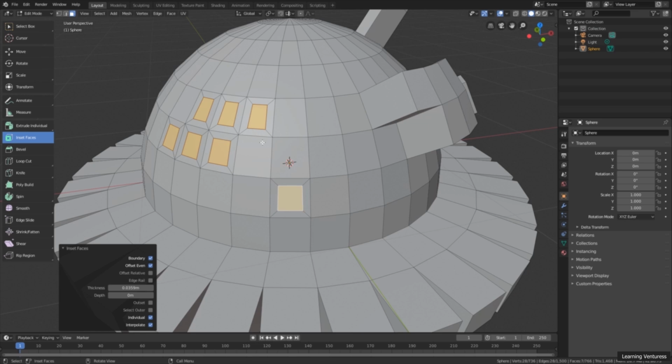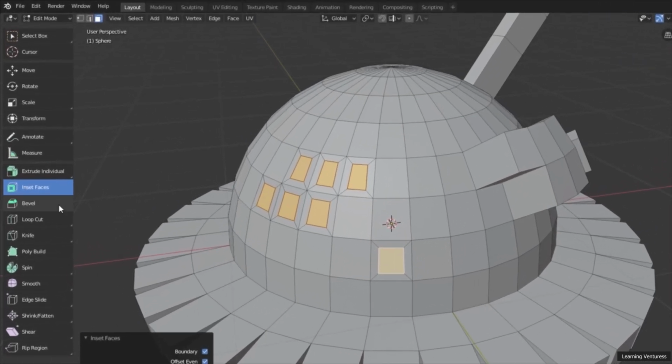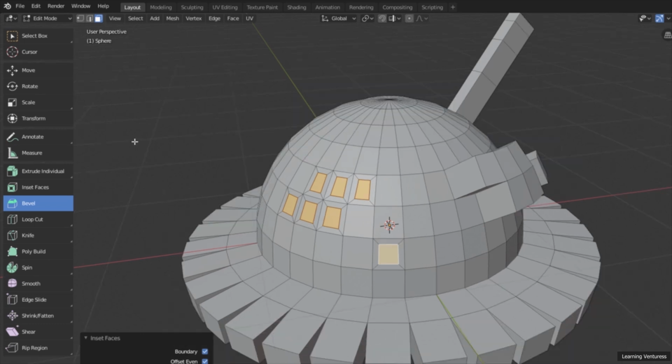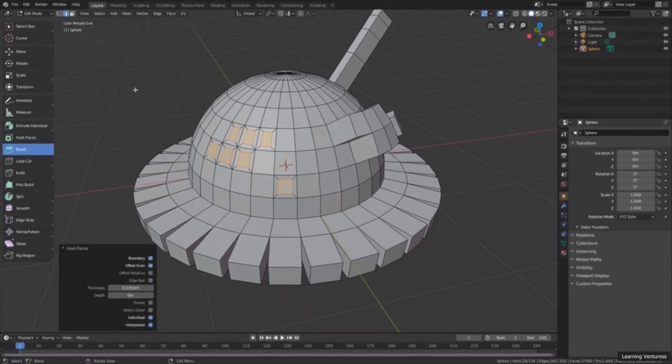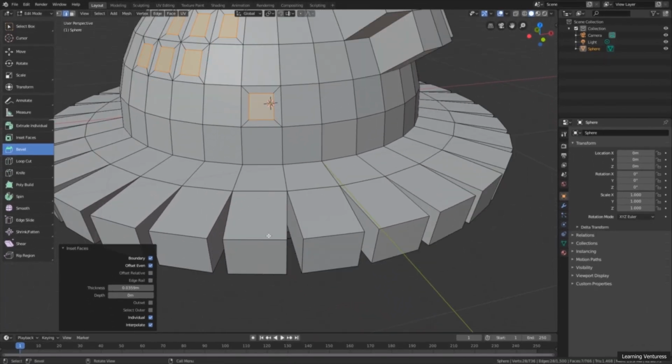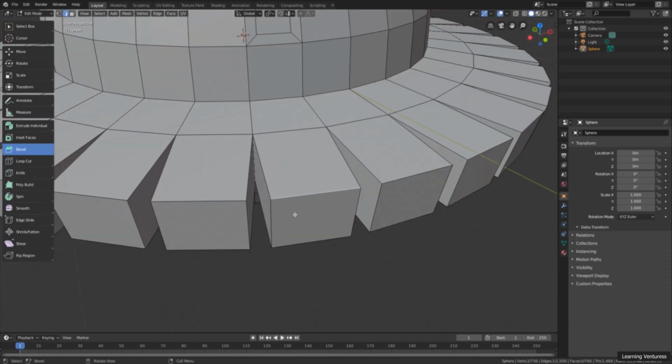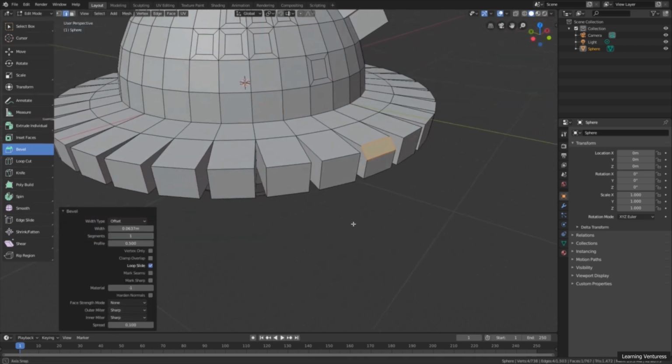And finally, let's take a look at the Bevel tool, which we activated right below the Inset tool here in the toolbar. To use this tool, I will activate the Edge Selection mode up here. And now, I will select one of those edges of one of those corners that we created with the Extrude. And if you have the Bevel tool active and click and drag, we will see that this tool splits the original edge in two, creating a chamfer on the selected edge.